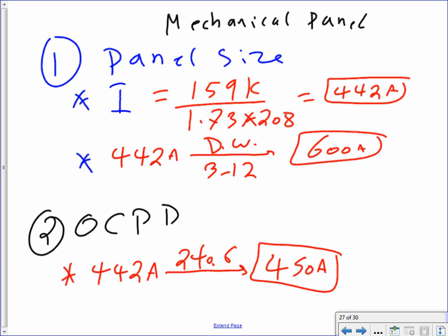If you drop that 450 into a 400 amp panel, would it work? Absolutely, it will. But what happens if it doesn't work? They hire you as a registered engineer to review my work, and you see me dropping 50 amps below, I lose the case in a court of law. Definitely. You can see how we design to cover all the unexpected issues.